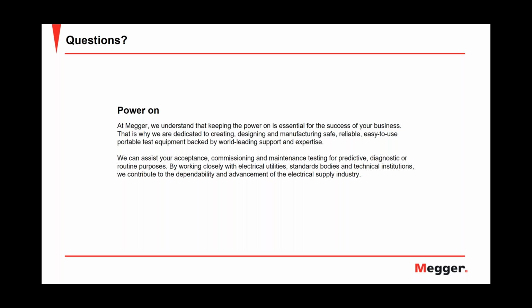Robert pointed out, typically you do the DC hipot test at much higher voltages. The old IEEE standard called for 5 times the phase to ground voltage, right? So on a 25 kV cable, you would use 70 kV DC, okay? And also the time is much longer. And I think the example that Robert used on the 25 kV cable with 19.9 phase to ground voltage,